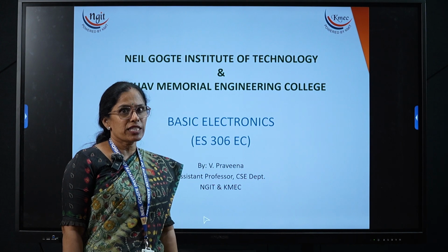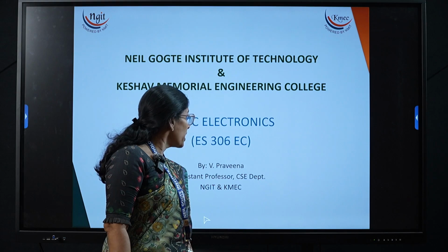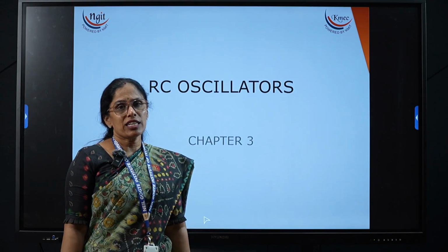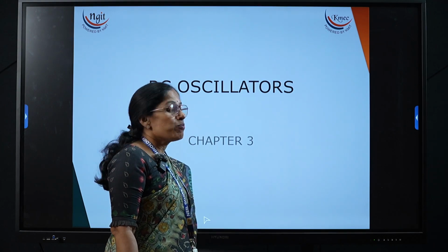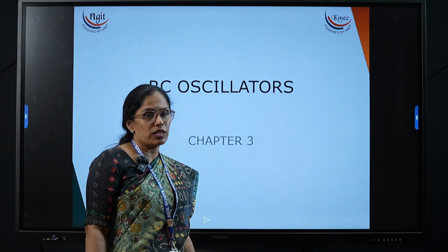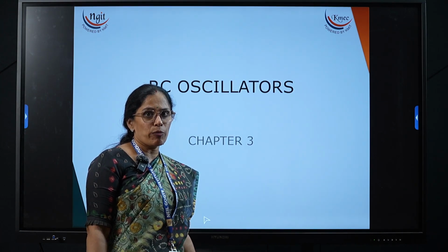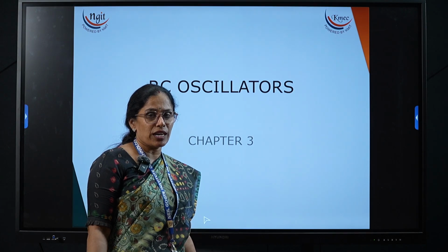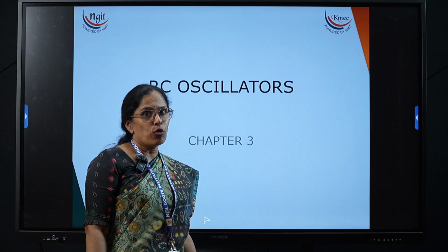In this lecture, we discuss RC oscillators. In the previous lecture, we discussed the LC oscillator. LC oscillators we use for generating high frequency signals. To generate low frequencies with LC, the size of L increases. That creates complications in the circuit, cost, size, everything. That's why we use RC values to generate the low frequencies.